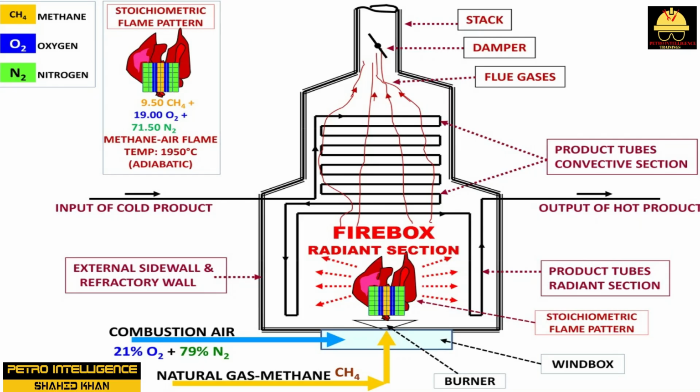Furnace efficiency. Running furnaces efficiently is a major operating concern because 2/3 of a plant's fuel budget is needed for furnace fuel cost. Furnace efficiency is linked to environmental regulations that stipulate a clean operation. Most furnaces use fuel gas or fuel oil. Natural gas burns cleaner and more efficiently than oil. In a natural gas furnace, oxygen and natural gas combine in the right proportions at the burner. In an oil-burning furnace, steam is used to atomize the oil and mix it with air at the burner tip.